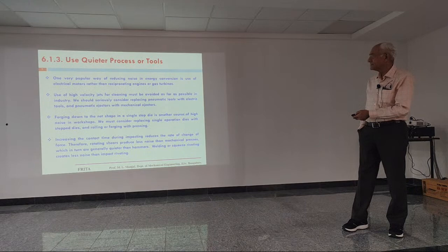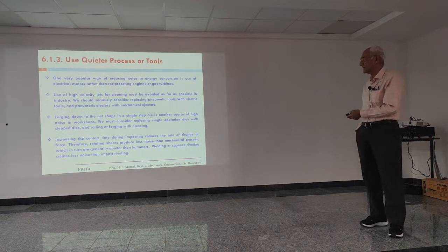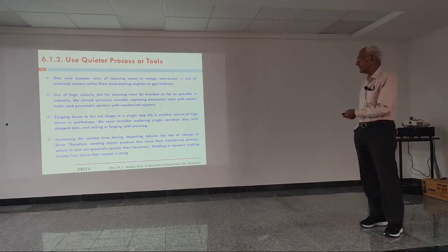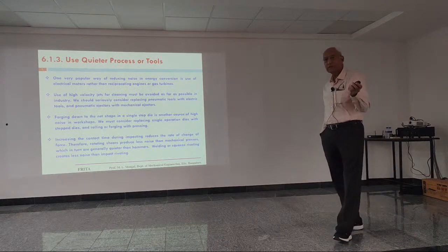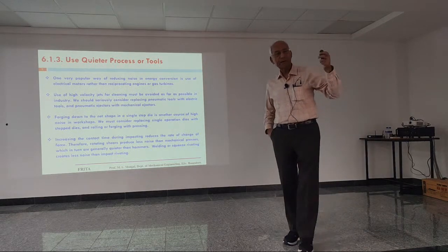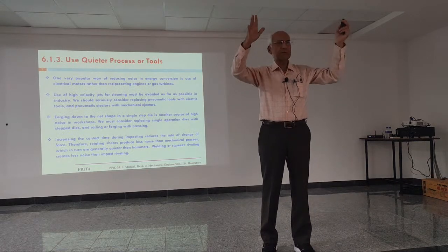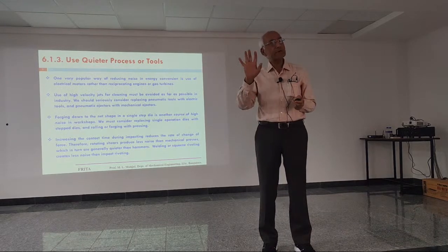Other is use of high velocity jets for cleaning must be avoided as far as possible in industry. We should seriously consider replacing pneumatic tools with electric tools and pneumatic ejectors with mechanical ejectors. This is something you must have seen if you go to any sheet metal kind of workshop. But noise will be so much that you really regret that you came into that. And most of that is all self-created.